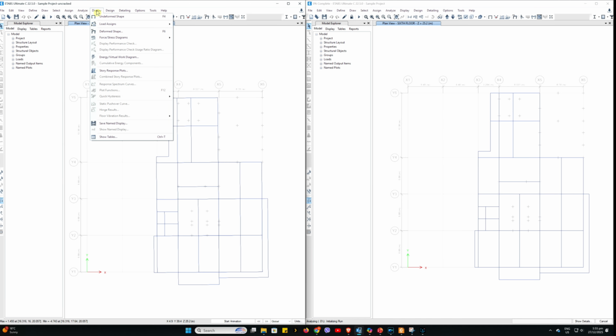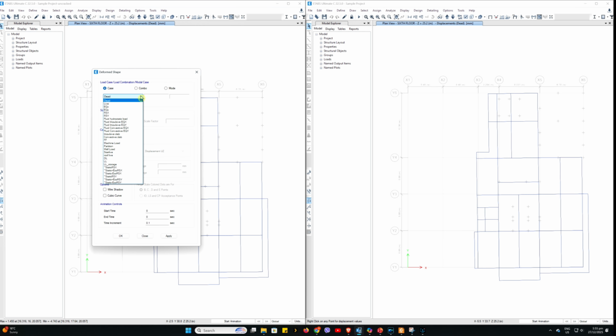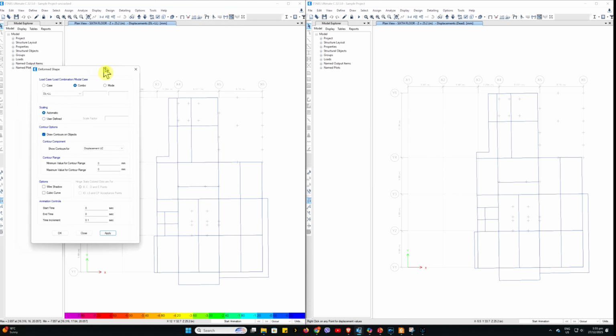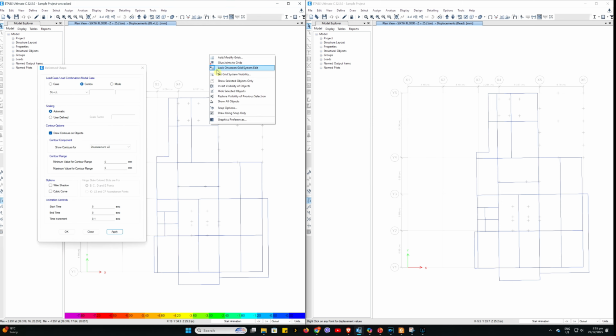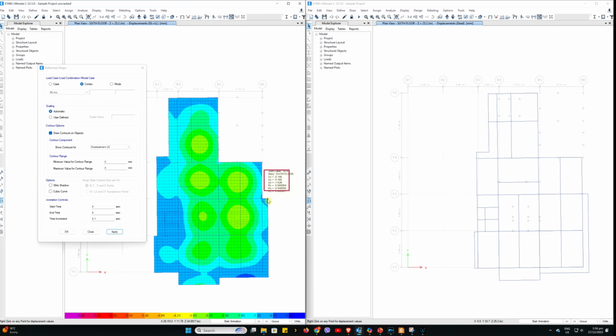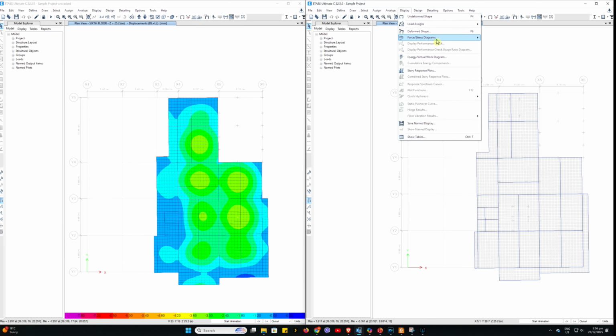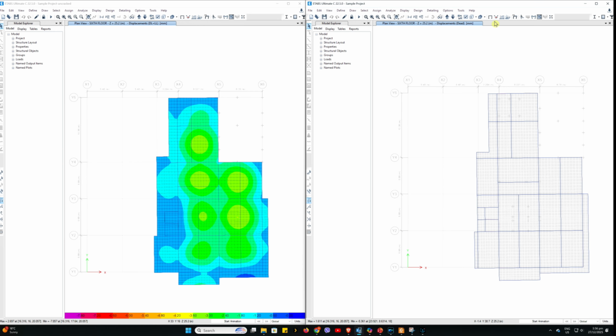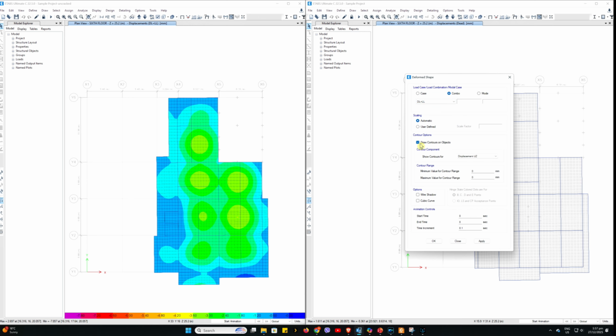However, due to modification factors, the internal forces are redistributed in the cracked model and primarily reduced in beams and columns. Similarly, deflection for service loads like dead load and live load also differ in them. The cracked model deflects more, which is realistic.